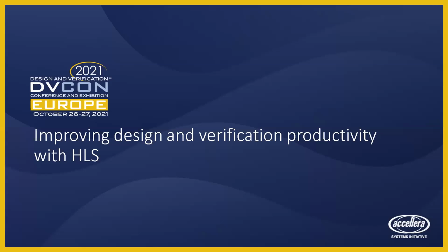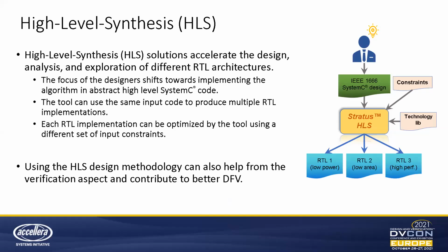So now let's consider how high-level synthesis methodology fits into this topic. In general, high-level synthesis accelerates the RTL design, implementation, and optimization phase. HLS designers are focused on writing abstract algorithmic SystemC code and then let the tool deal with low-level implementation details like building state machines, pipelining, partitioning, etc.